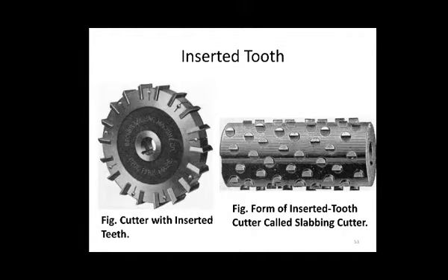To make an economical serviceable cutter of large size, it is customary to use a cast iron body with inserted tool steel teeth. There are several different methods of inserting and holding these teeth. Usually, when the inserted tooth is in the form of a blade, it is held by taper pins or screws.